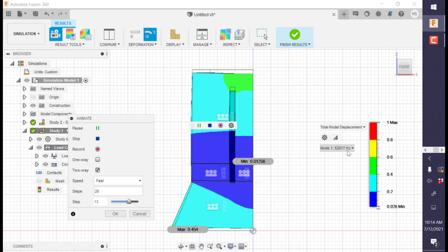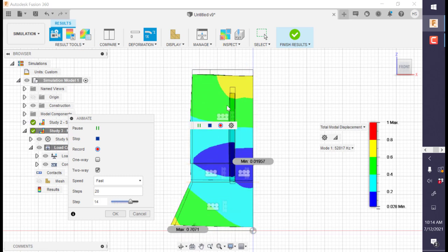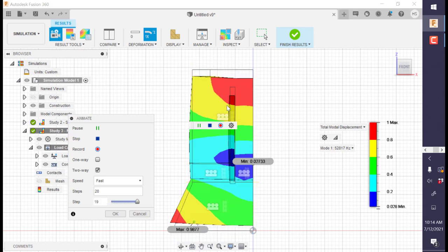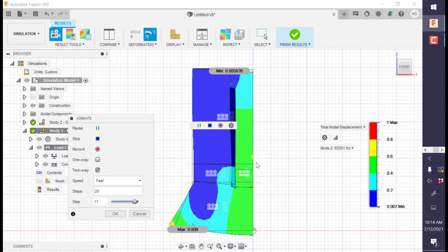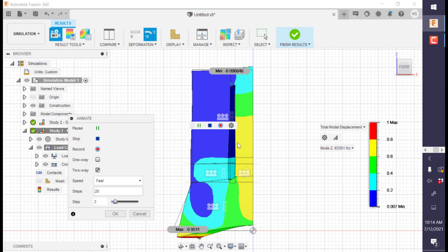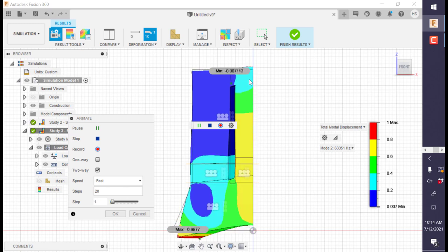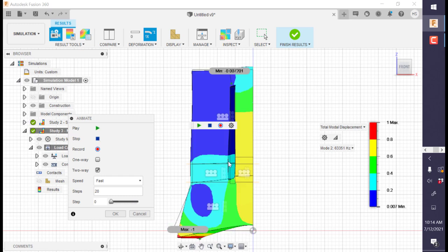The interesting thing now is looking at a higher mode of resonance, another permissible way that sound waves can bounce off, creating constructive interference or constructive amplitude and gain in your transducer. So we'll look at the next mode, and it's very interesting. In this mode specifically, we have significant excitation and movement in the center bolt itself. We won't have a strong excitation from your piezo ceramics because the center bolt here is going to be the most active.